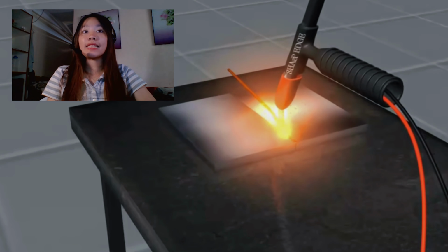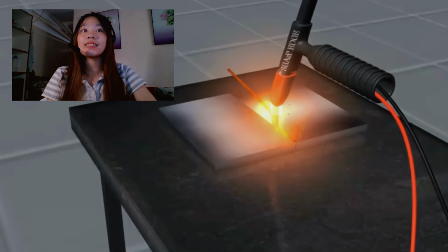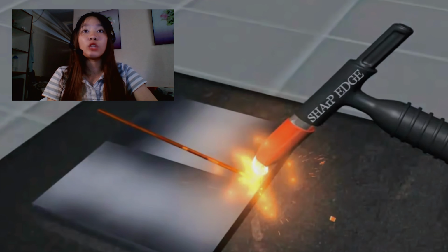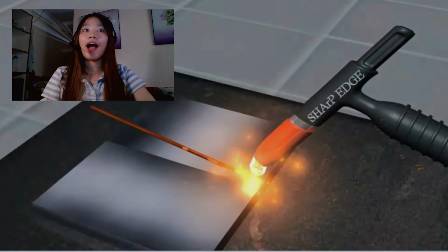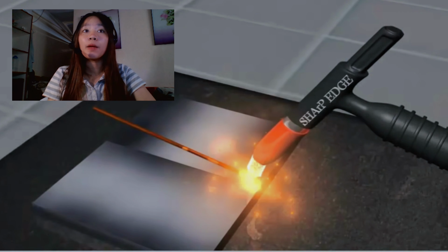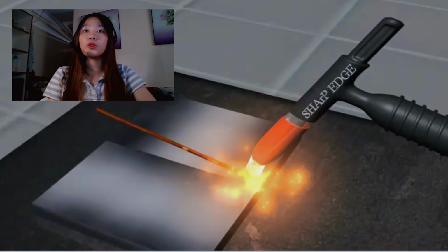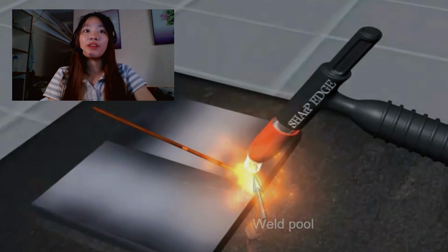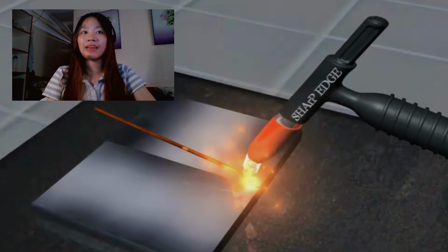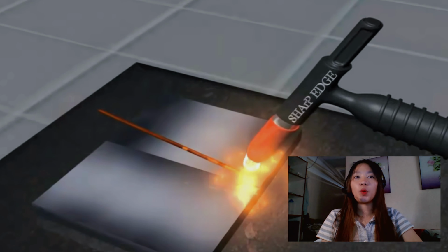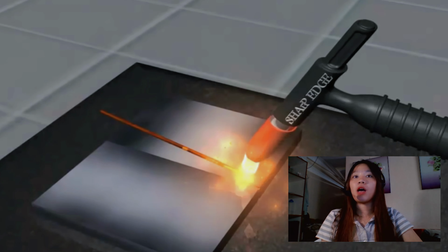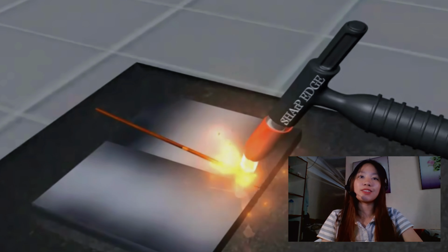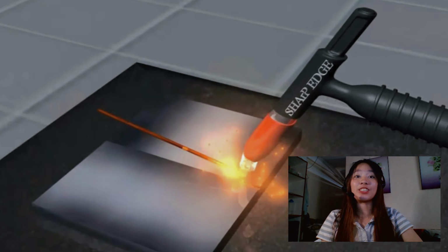While maintaining a constant separation between the electrode and the workpiece, the operator then moves the torch back slightly and tilts it backward about 10 to 15 degrees from vertical. After that, filler metal is added manually to the front end of the weld pool as it is needed. Welders often develop a technique of rapidly alternating between moving the torch forward and adding the filler metal. The filler rod is withdrawn from the weld pool each time the electrode advances, but it is never removed from the gas shield, to prevent oxidation of its surface and contamination of the weld.